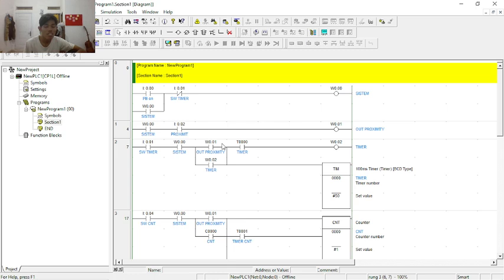In the demonstration on trainer board, we can see that we cannot see, but maybe you can try, or maybe when we execute the program, the proximity sensor mount near the cylinder. When we move a metal object close to the inductive sensor, its indicator LED turns on. The signal is sent to the PLC input on the CX programmer monitor, so you can see that the input bit turned on as well. But we cannot connect to the PLC.